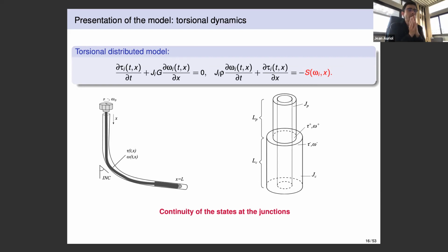Yeah, and from a mathematical point of view, if you add the axial dynamics, then you have a non-scalar equation, because you have axial plus torsional. We have recently obtained some results to deal with interconnection, in the absence of friction terms, just for linear PDE-ODE systems. So a possible path to follow would be to adjust the kind of adaptive observer we have with these new observers we have derived for linear ODE-PDE-ODE. But one problem might be that the different coefficients might not be distinguishable. So as Florent said, we may have to do it in four steps, estimating one coefficient after the previous one.